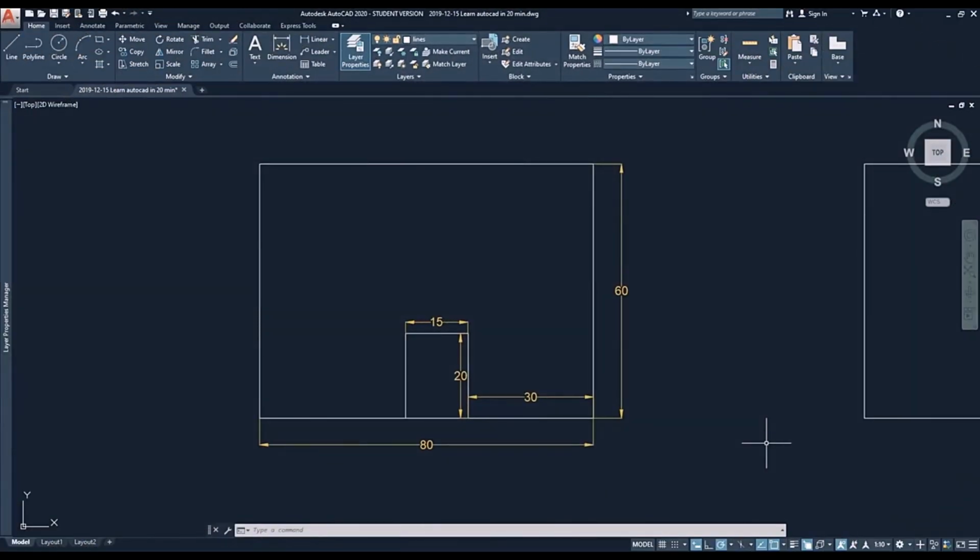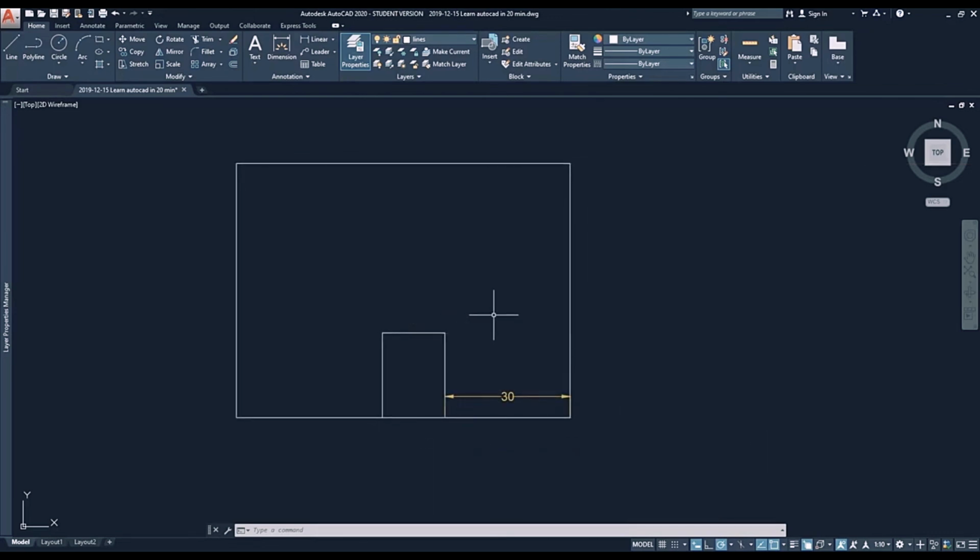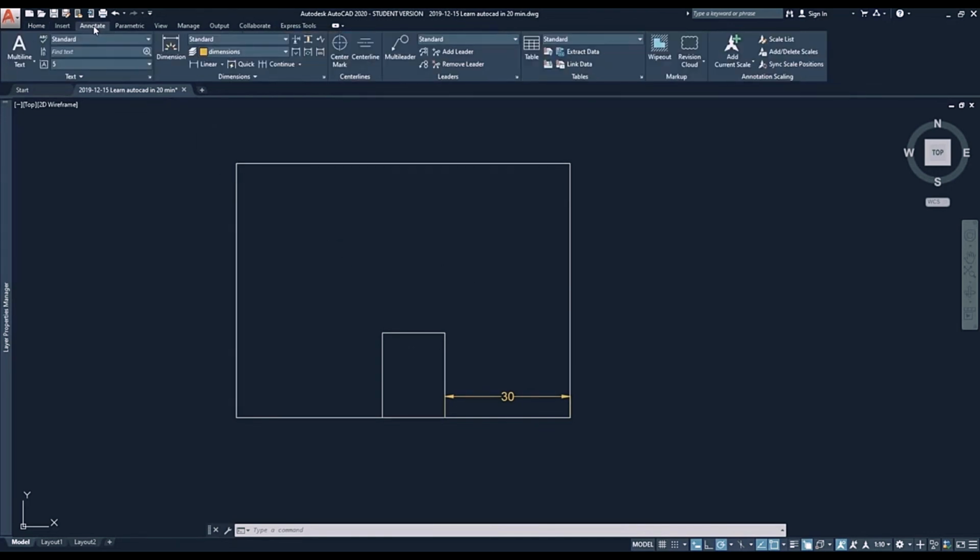Part 6, the final part. Dimension lines. Now I am going to teach you how to draw dimension lines. This is a classic feature for annotation in your drawings. In this figure, you can see the dimension lines indicating its distances. Now, to draw dimension lines, there is a panel on the Home tab here. Or if we go to the Annotation tab, we can have all the tools.